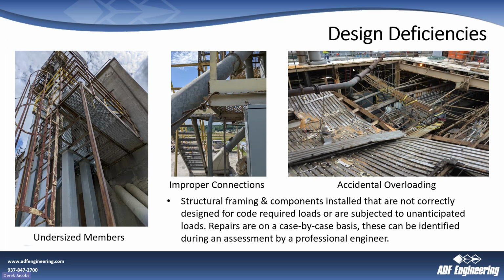We also have here, maybe a little harder to see, guy wires for some type of process stack that are tied either to something that's not sufficient to support the reaction from them, and also maybe tied incorrectly. I think this one here only has one buckle, which is not compliant.